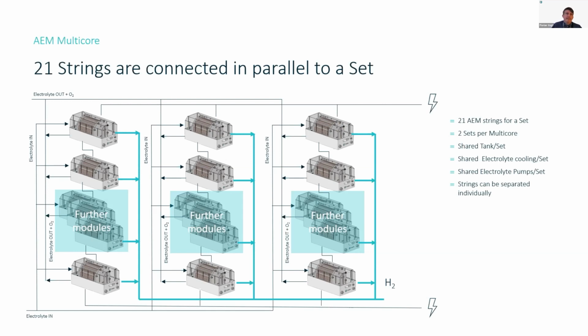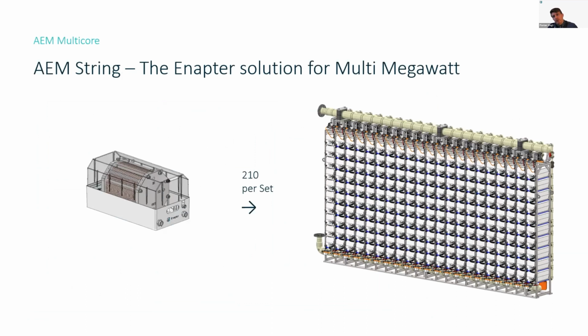So basically it looks like this. It's a little bit like a bookshelf. It's on the left, not on the right side of the container. Here you can see 220 electrolyzers in our bookshelf, in our rack on the left and on the right side. They are connected hydraulically in parallel, and the gas is also collected in parallel. You can see these are 10 stack modules, and all of these have 1 power supply unit. So 1 power supply unit is for these 10 stack modules.